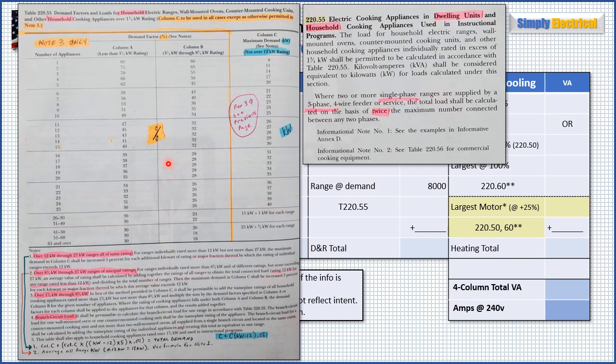If you are taking a test, if it asks you for the minimum, which usually what it'll do, it'll ask you for the minimum value for a particular appliance in a given situation, you'll need to go to column A or column B, because that's generally going to give you a lower total than what this will. Column C is kind of the catch-all, and it usually adds a little bit of cushion over what A and B will give you for the same appliance.